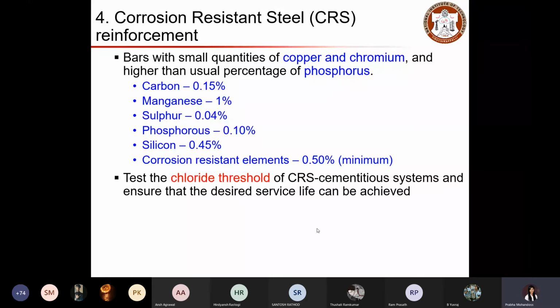And then in addition to that, you can do bend test. You can keep your rebar and bend at 135-degree angle and see, are you observing any crack on the surface. If there is a crack, that indicates you're using a poor quality rebar and you can discard the batch.